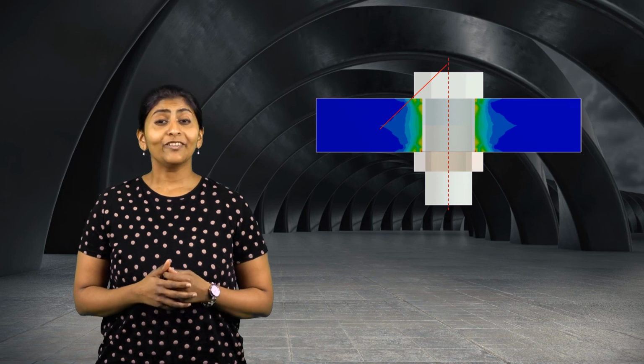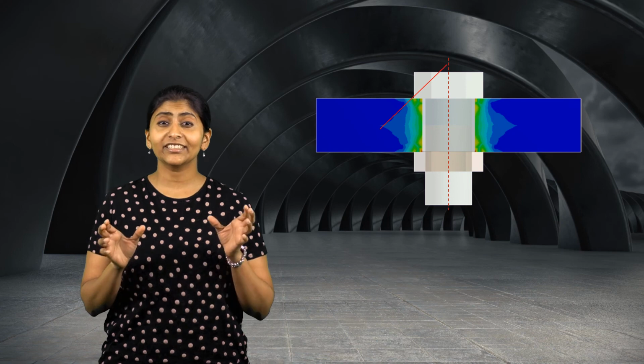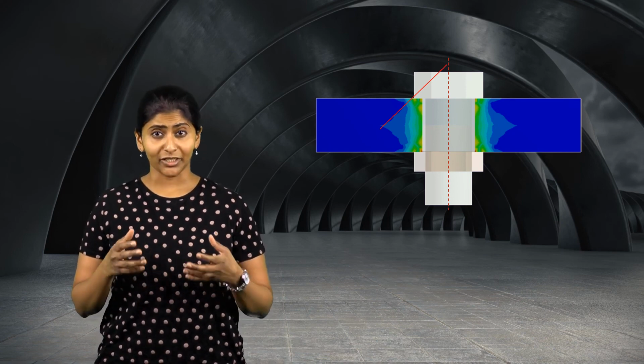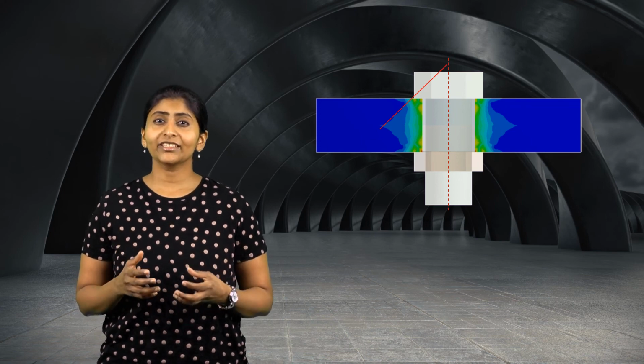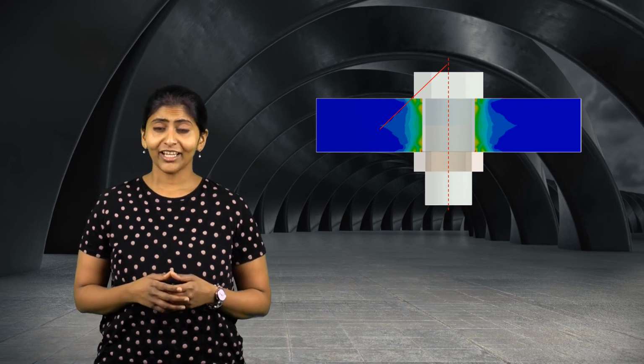Let's revisit the concept of pressure cone. We can see that proper sealing can be achieved when the pressure cones of adjacent bolts are closer. In order to increase the size of the pressure cone, one can also change the diameter of the bolt. But by what extent? Well, let's use Ansys again to run a series of simulations and pick the correct size. In order to do this, we will perform a parametric study to avoid manually running the simulations for different bolt sizes.